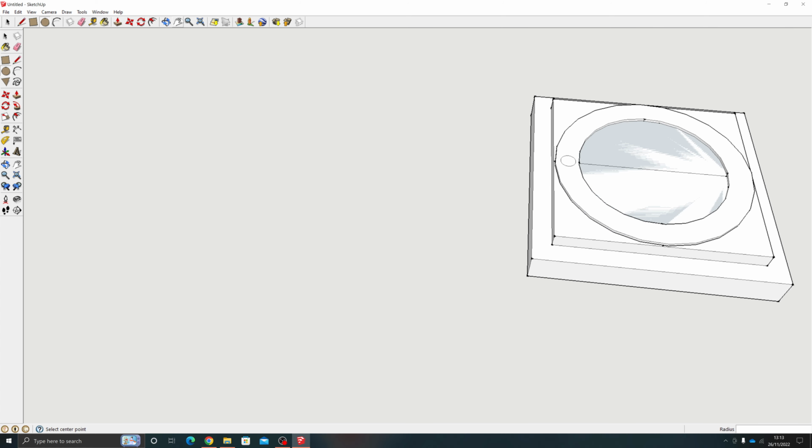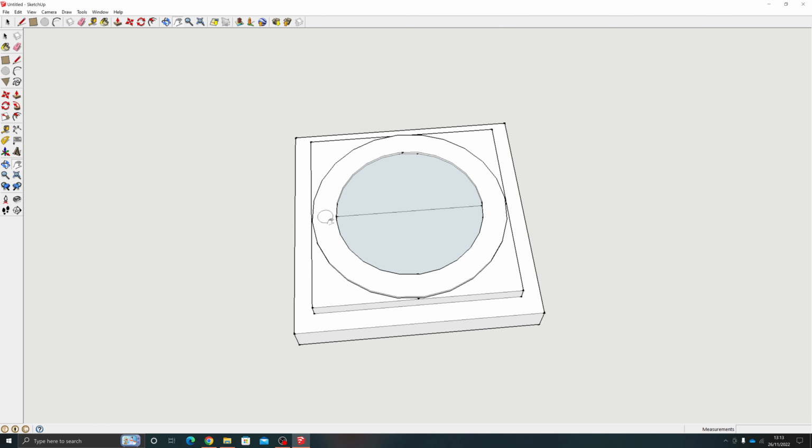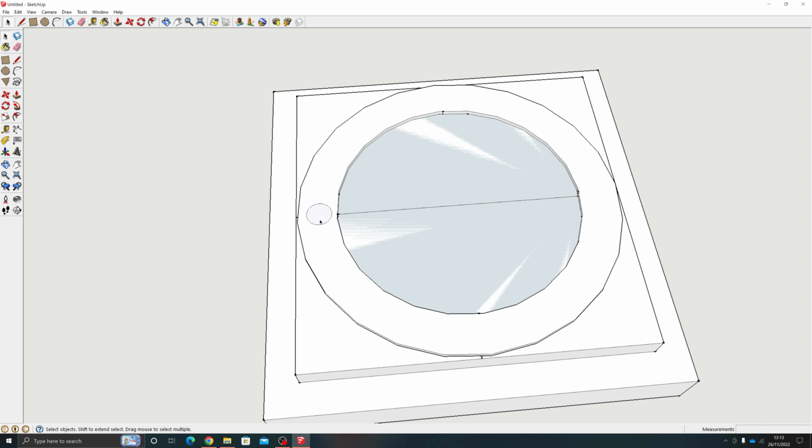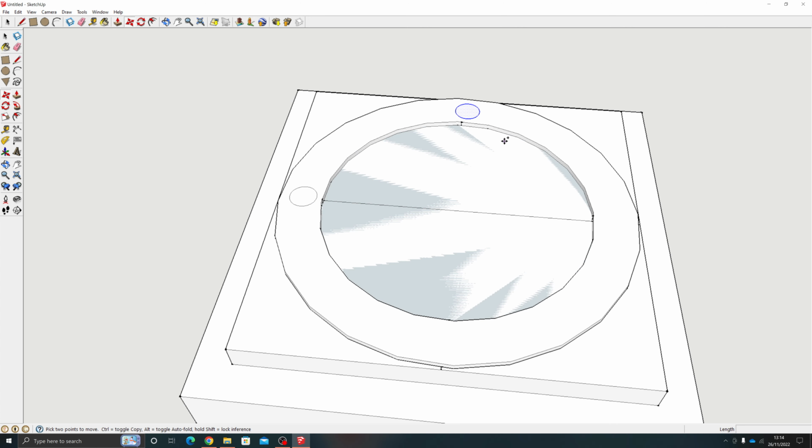Now, it can be quite hard to get these all lined up. So what I tend to do, and a bit of a tip, is select your circle shape, the circle you want. I'm going to have mine in 4 positions, so I've got to add another 3. Rather than copying and pasting and then trying to guess where I put them to make them look right, I use the rotate tool.